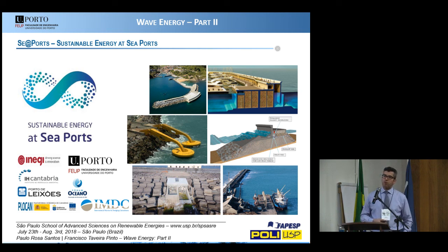The innovative part of this project is that we intend to combine two different concepts to harness energy. So it's not a hybridization combining technologies for different resources. The idea here is to combine different concepts to harness wave energy and integrate them in a single model. That's the point here. We have two case studies, one in Porto and the other in Las Palmas. The idea is to have two representative ports. In the port of Leixões, we have a rubble mound breakwater, and in Las Palmas, we have a vertical breakwater. So we are developing solutions for different geometries of breakwaters.